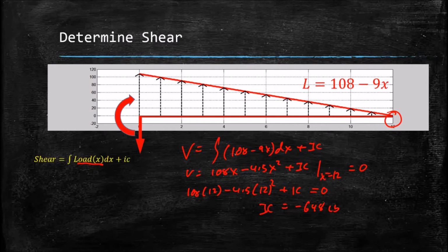And if we had done the triangle calculation, we would have got the same answer. And so that tells us that if this is 648 downwards, somewhere in here I have some equivalent force equal to 648, but in theory we don't know where that is quite yet. And the other thing we should do is be careful with our signs. We have an upward force, and that's going to result in our downward reaction force. That's a negative force in our up and down convention.